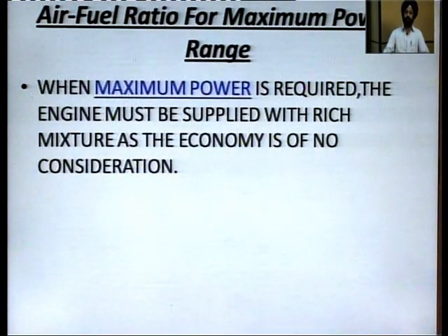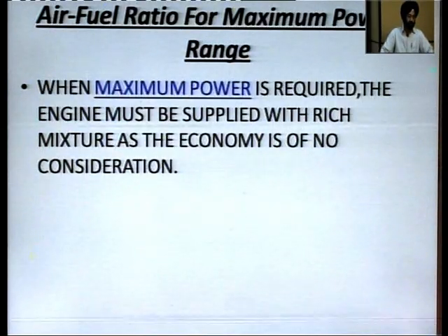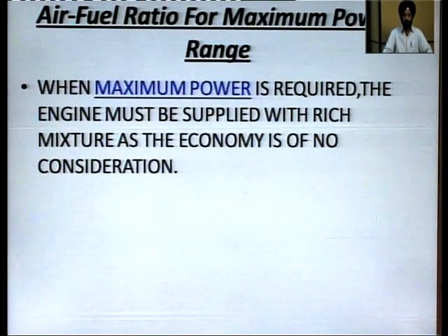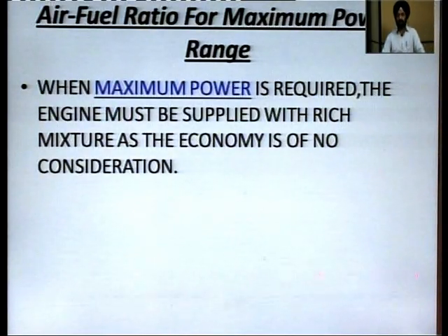For a multi-cylinder engine, slightly more fuel is required due to maldistribution of the fuel. Now, air fuel ratio for maximum power range. When maximum power is required, when we are going up a hill or the car or truck is loaded, then maximum power is required. So, what type of air fuel ratio do you suggest? It is a rich mixture, because economy is not a consideration. The thing is that the engine should not stop, it should be a highly ignitable mixture.